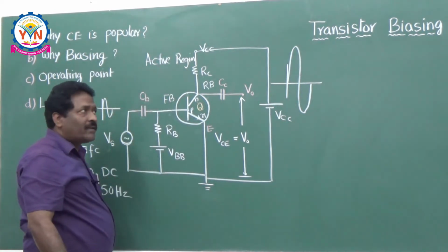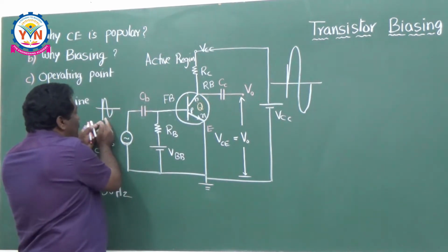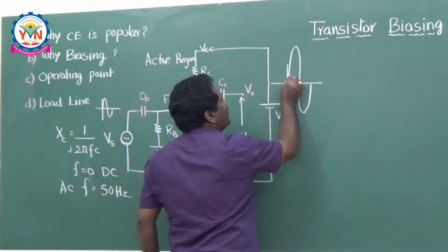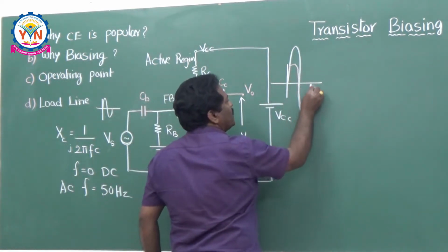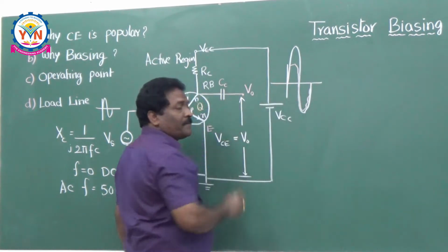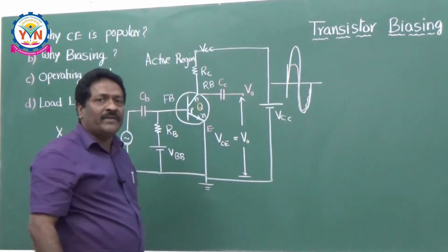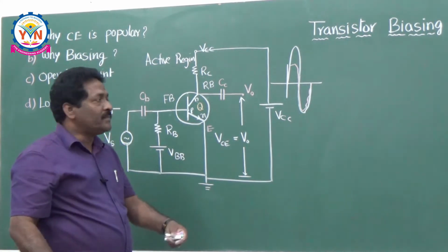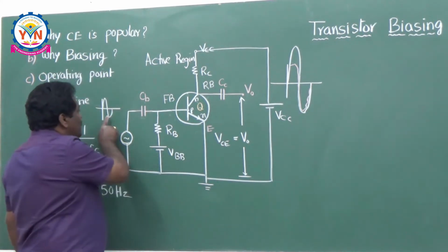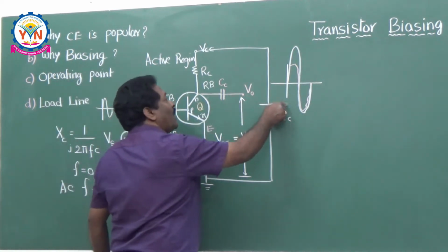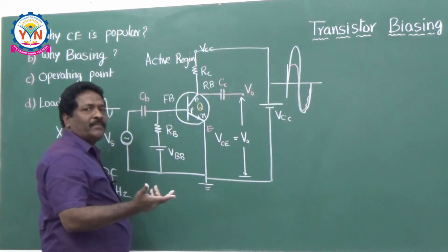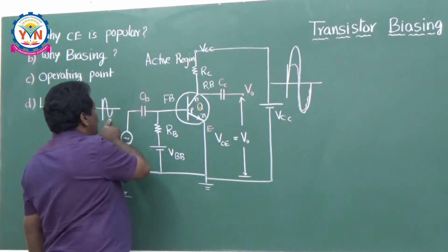transistor. Otherwise, suppose you are passing the signal to the amplifier, and it comes out in this way, like this, that means the shape is disturbed here. That means it is not faithful amplification. Information is lost. So that's the reason. Remember always, the shape of the signal should be the same. Of course, the magnitude will be different, because amplification means very simple, my dear friends. You are enhancing the signal strength.